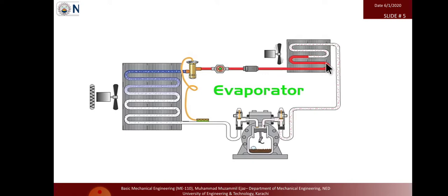By the compressor you have a high pressure, high temperature refrigerant, and by the expansion valve or capillary tube we squeeze the volume and then place it in a larger diameter volume. Doing that, the pressure will reduce, and due to the reduced pressure the refrigerant gets cooled down.